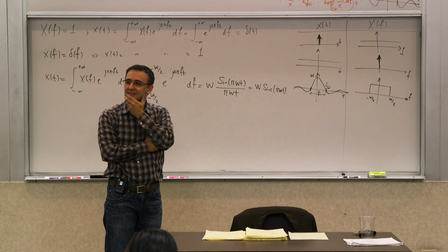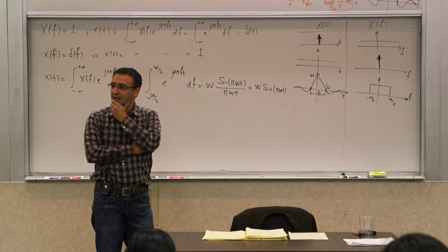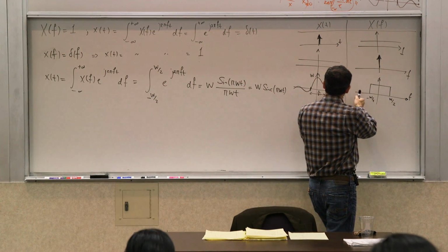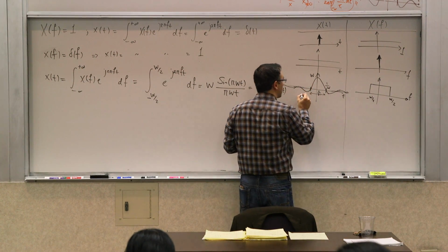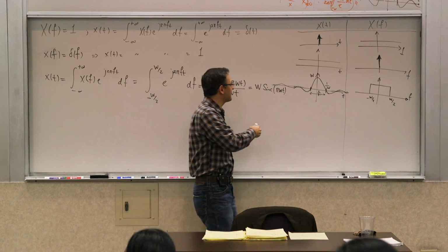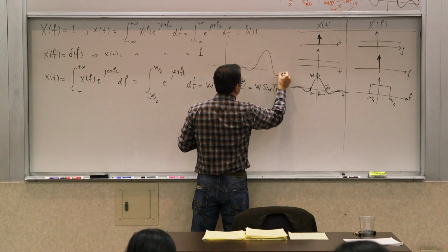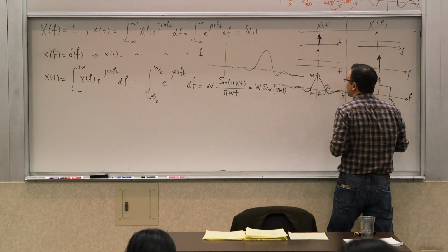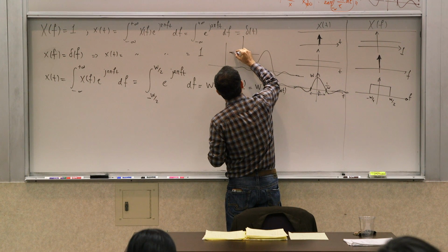When you made a filter like that, would you have a time delay on the signal? Yeah. So if you allow for a time delay, if you let this be shifted here, now sinc never goes to 0. It diminishes, but it doesn't really quite go to 0. So at some point you may say, I can truncate it, and instead of this, have a system whose impulse response looks like this. And this would then produce a filter whose frequency response or pass band wouldn't exactly look like that. It would kind of look like this.